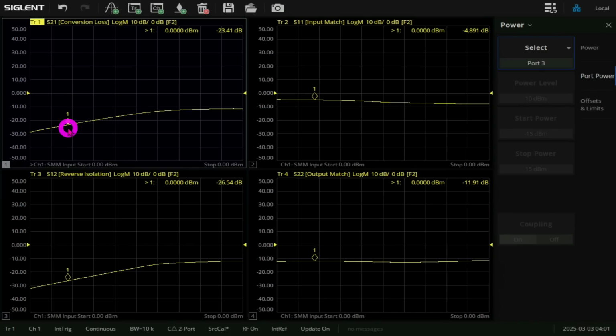So this characteristic that the conversion gain increases and flattens out up to a certain point is very much like how a mixer should behave, particularly a passive one. Now if I could increase the LO power even more, eventually it would dial back down, as the mixer would enter this horrible nonlinear mode, and then things would break down.